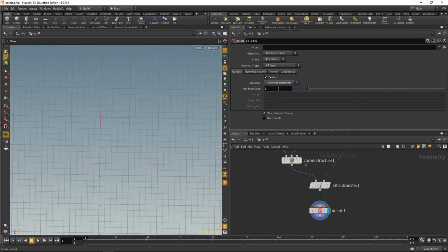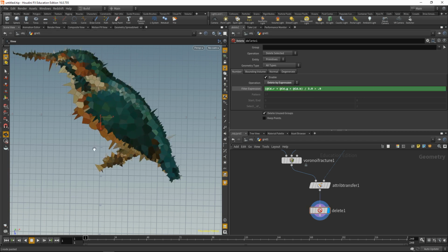And I'd like to check if the average color value, that means the average brightness, of a given cell is above a certain threshold. So what I'll do is add the individual color channels, then divide them by 3, and I'm going to check if that value is above 0.9, and then I will delete a cell, like so, before and after.